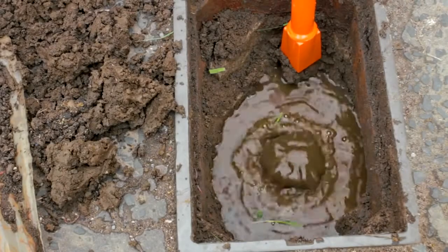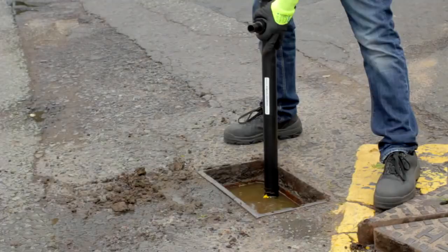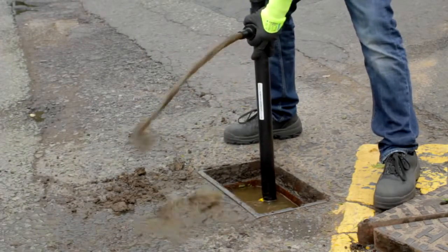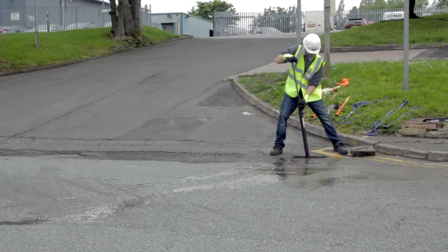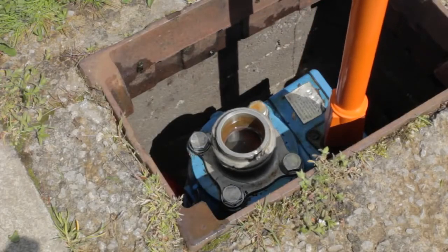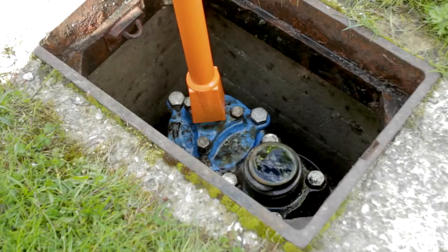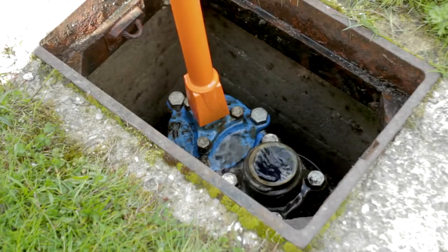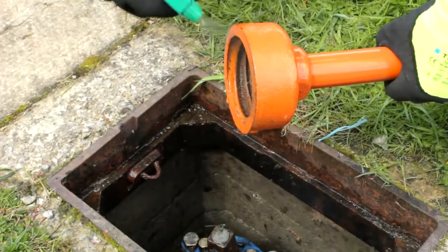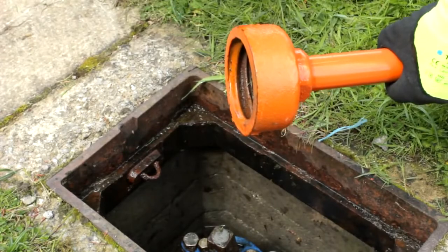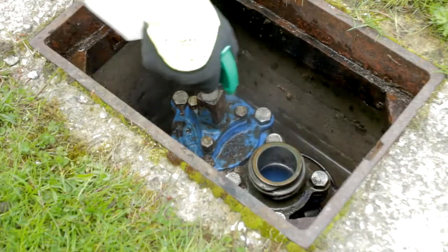Sometimes the chamber may be full of water. There is means of removing this by using a hog pump. Once prepared, just slightly open the hydrant, just to empty the contents of the bowl. Once complete, we recommend you use a chlorous solution spray on the outlet and base of the standpipe to minimise any contamination risk.